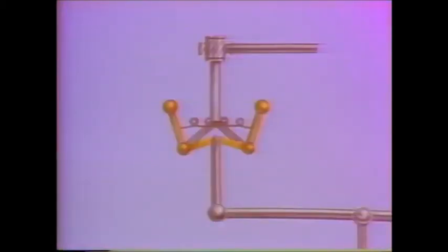The flyweight governor is composed of a shaft connected to the turbine by gears so that the governor spins with the turbine rotor. Two L-shaped brackets are attached to the governor by pivots. The brackets are weighted at the top of the L and are connected at the bottom to a rod that joins the governor to the crossbeam. A spring is connected to both L-shaped brackets.